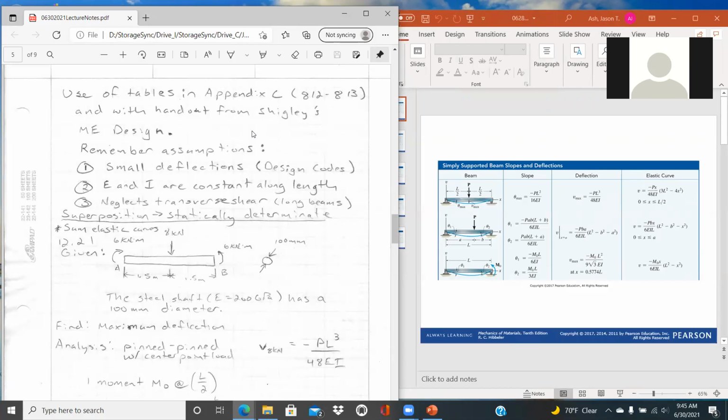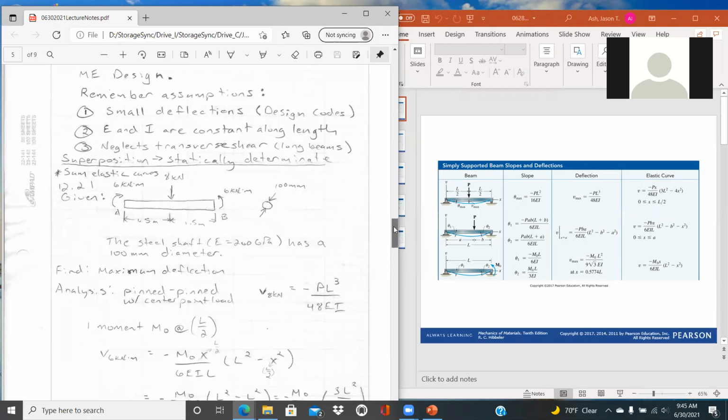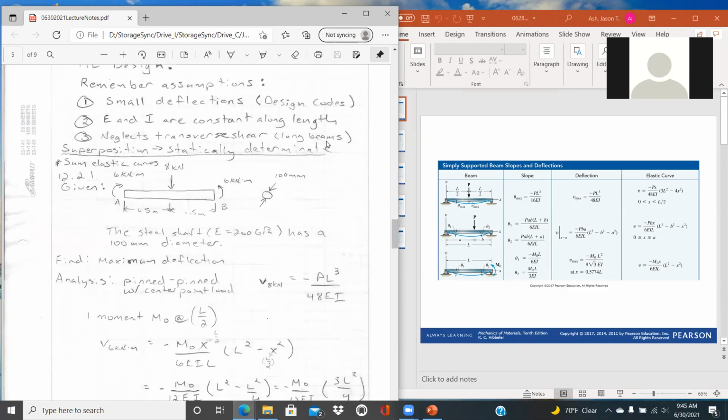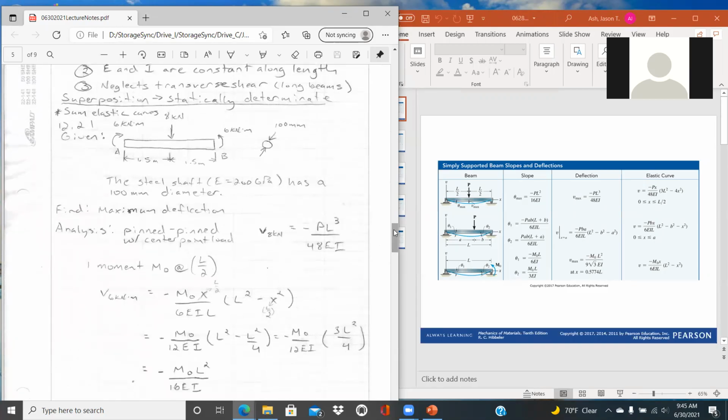And we might touch on that a little bit, looking at Castigliano's method. But those effects are generally negligible. And so when we're dealing with problems that have multiple loadings on them, really it's just a matter then of using that principle of superposition and summing those contributions together.